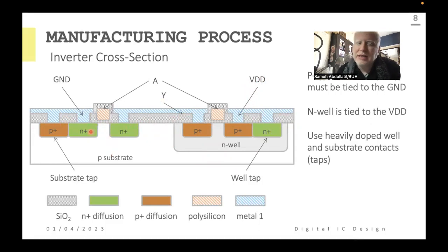You can see it very simply when you consider that you are applying VDD here, and then in the next portion of the wafer we have another ground here. So there might be a flow of current or a short circuit connection between this VDD and the adjacent ground and vice versa.